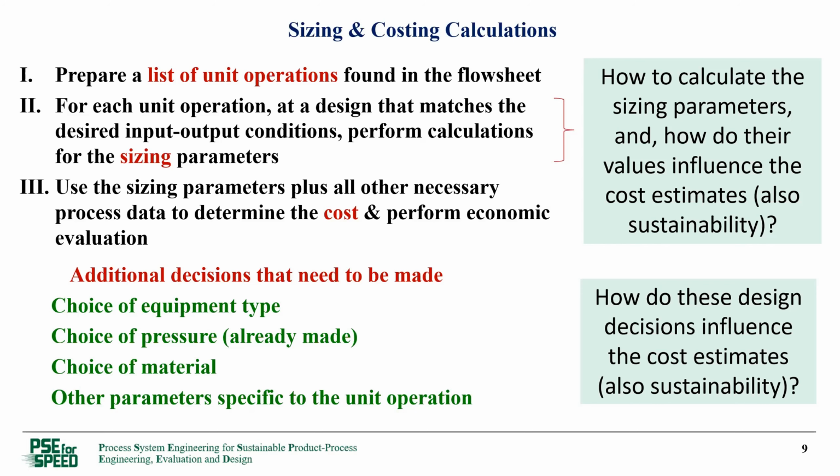That depends on what kind of operation we have, what kind of safety we have, what kind of reliability we need, and also what chemicals are involved. Obviously, if there is water, the carbon steel cannot be used. Stainless steel needs to be used because of corrosion issues.